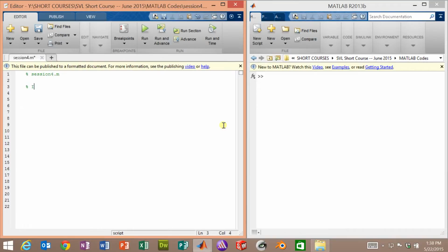So as usual, the first thing I like to do is initialize MATLAB. I close all the figure windows, clear the command window, and the most important, I clear memory. Now I'm going to define a unit, and the only one we'll need here is degrees. I define that as pi over 180. This lets me create variables such as theta equals 45 times degrees. I think it makes the code a little bit easier to read and to follow, and it helps me think through the code.